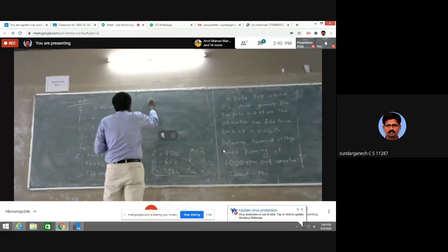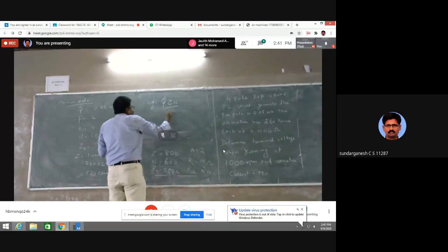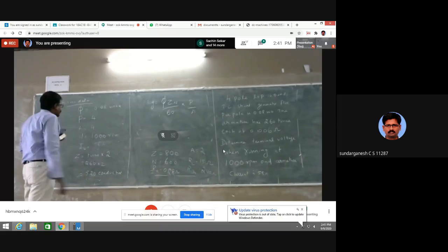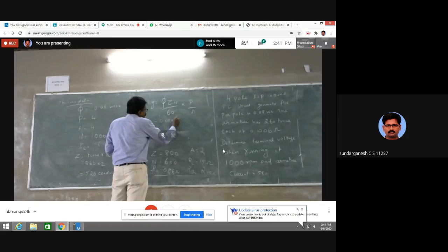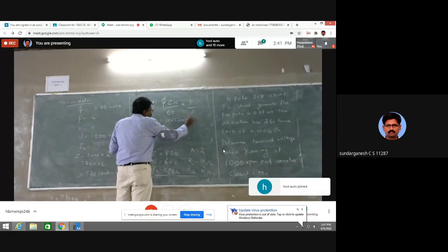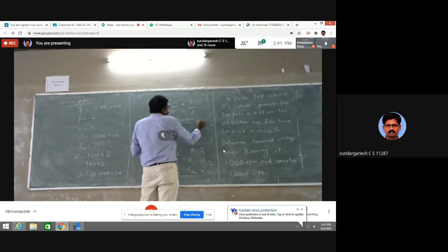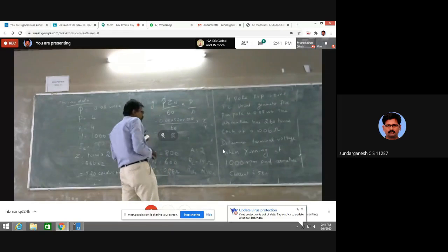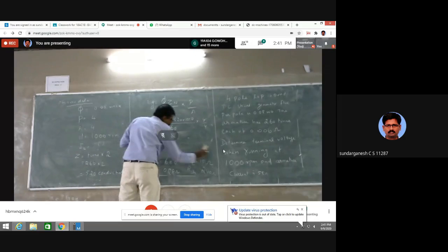EG equal to phi Z N by 60 into P by A. So phi is 0.08, Z is 520, N is 1000, 60, P and A are equal, 4 by 4. So you get the generated EMF.